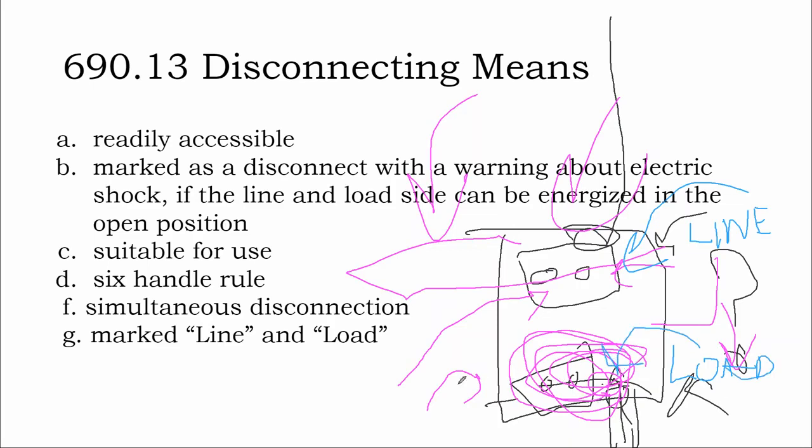And in this case, even though you have the grid, which is obviously a supply, you might also have the solar array, which might not have any load circuits on it. So you say, okay, well, which goes into the top? They're both supply. The grid's a supply, the solar array's a supply. Which one lands on the top of the disconnect switch?